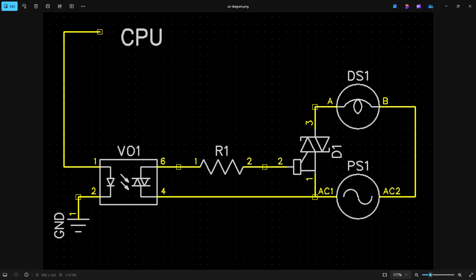Okay, so let's take a look at a schematic of how this would work. This is basically a solid state relay. This is our Triac right here. We've got AC coming in with one leg fed into one side of the Triac, the other leg fed into our load. Coming out of our Triac, our load, which is a lamp, is connected to this other side of the Triac. And then the gate runs in, and we put a resistor in here. We run it through. This is a Triac optocoupler. They're special optocouplers designed for Triacs, and we'll look at some data sheets on these in a moment.